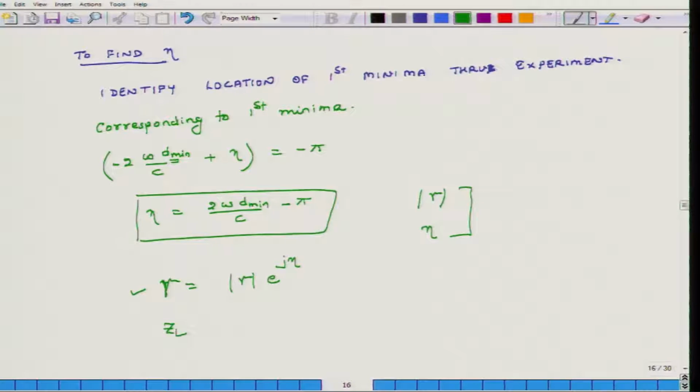Okay. So, this is the overall approach, and through this approach, using a Kundt apparatus or a Kundt tube, we can compute ZL if we are able to measure pressures in the tube at all the locations. So, that is the conclusion for today's lecture.